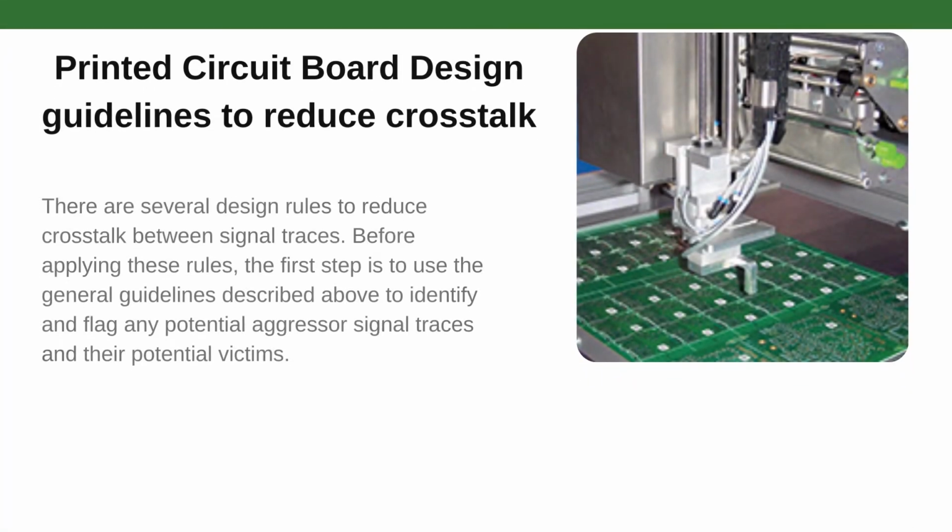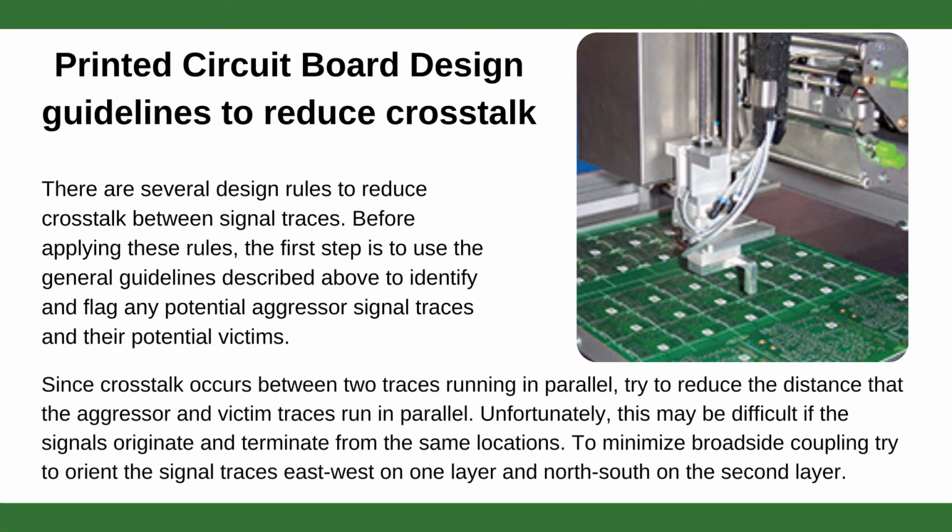Printed circuit board design guidelines to reduce crosstalk. There are several design rules to reduce crosstalk between signal traces. Before applying these rules, the first step is to use the general guidelines described above to identify and flag any potential aggressor signal traces and their potential victims.